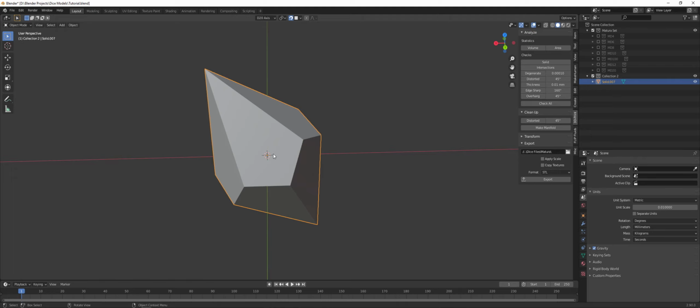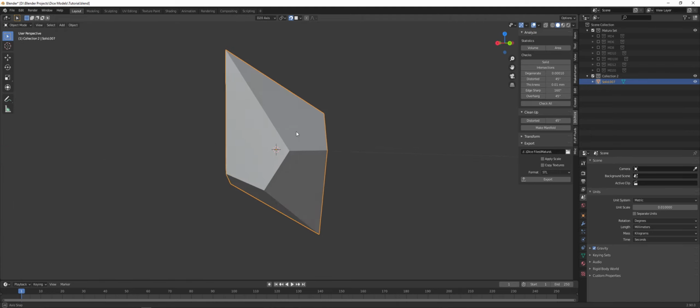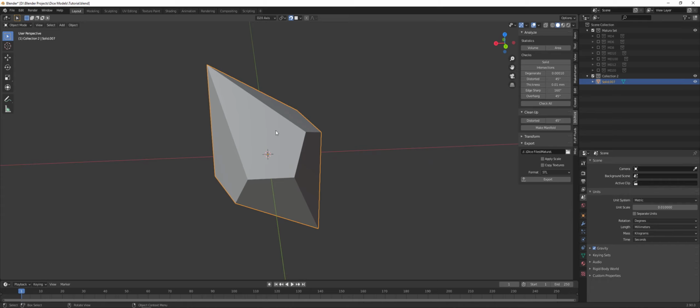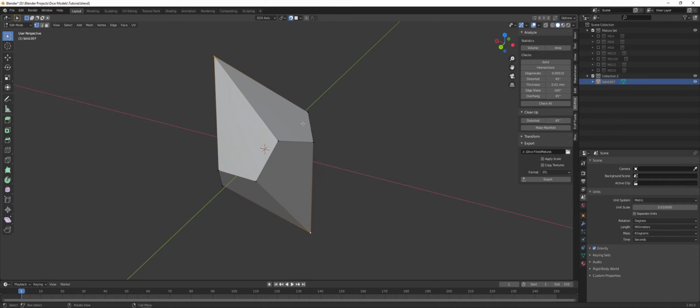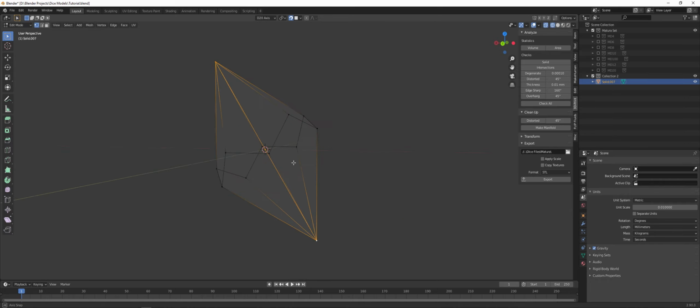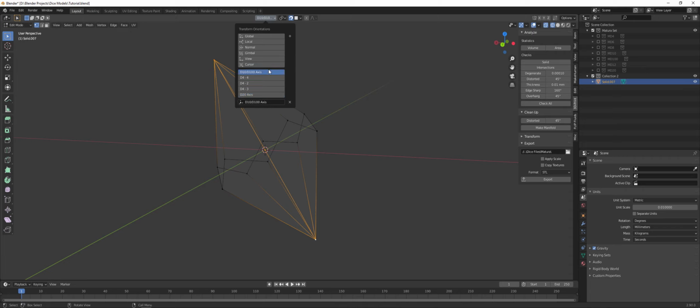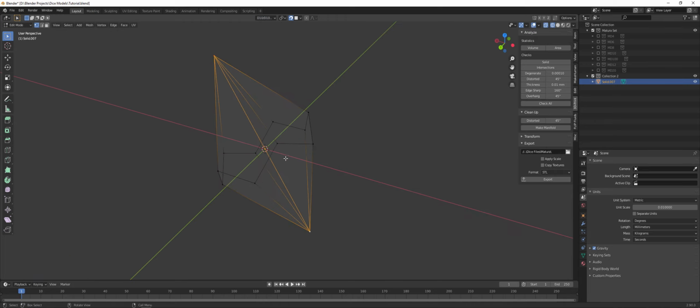Now, before we do anything else, I'm gonna suggest you choose which scale you want for your D10. So you're gonna create an edge with F between those 2 vertices, the top and bottom. And you're gonna use that to create a new orientation with this button, which you're gonna name D10/D100 axis. It will also be the axis for the D12, by the way. And with that, you delete the edge because you don't need it.